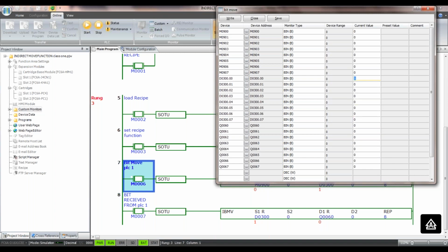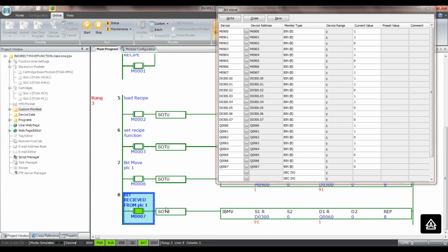So we'll start over again. I'm going to take M9. I'm going to turn these bits on in a PLC. I'm going to transfer these to a word, and then transfer it from the word back to outputs. You'll notice that now all 3 sections, all the M900 through 907, the word, and all the output bits are all the same.